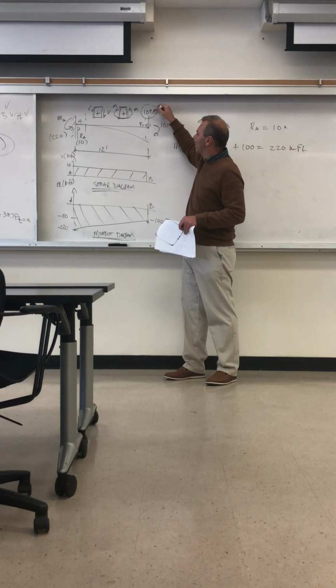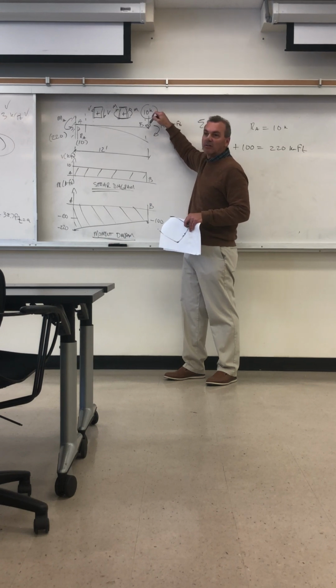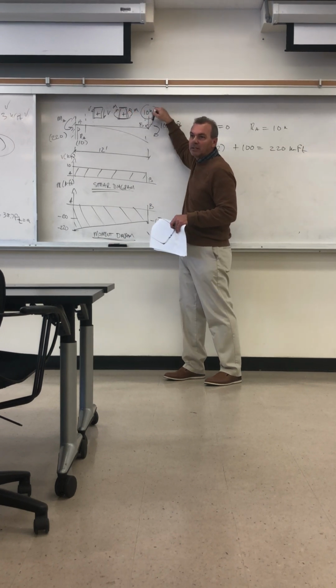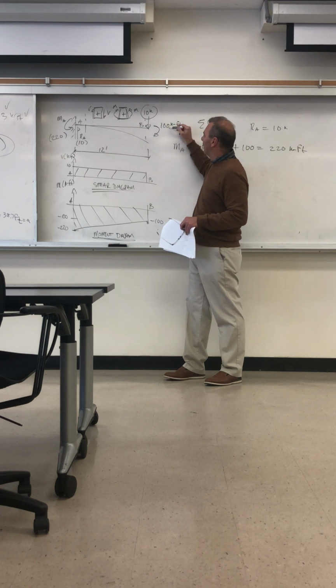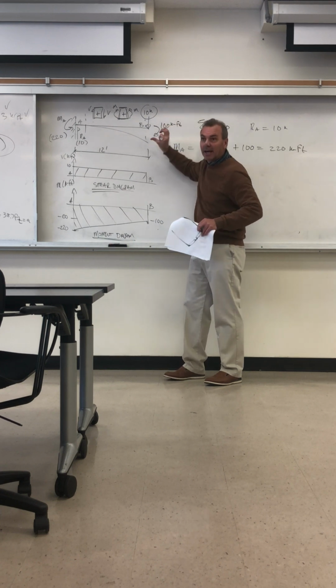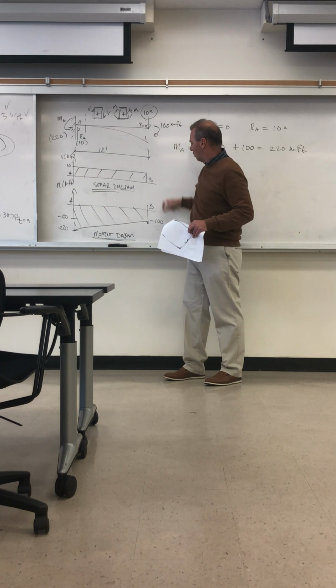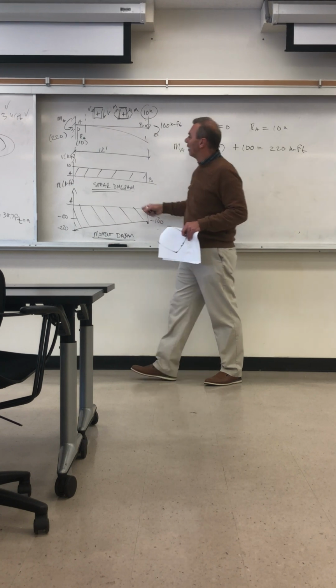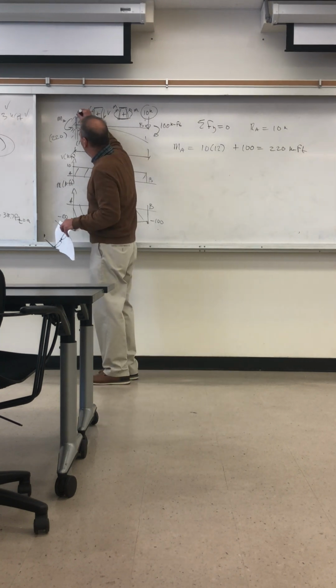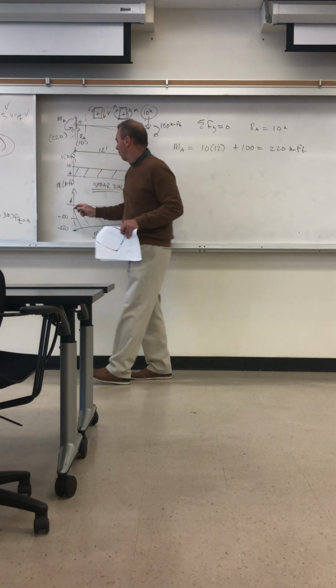But there's no moment contribution from the applied force at this location. It takes distance for this part to develop. So the only moment at B is this external moment, cranking like that. So it's putting minus 100 right there. And then on this side, if you take a cut, the only moment is this reaction on the wall, which is minus 220.